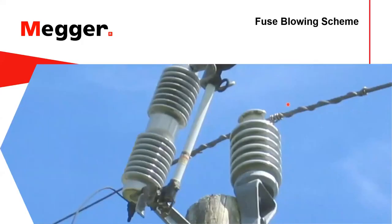Now we're going to talk about fuse blowing schemes, but before we do, let's just take a moment and recap fuse saving. Very briefly, fuse saving permits whole feeder momentary outages. The intent is to prevent longer outages to the entire faulted circuit. Fuses will accumulate a little bit of damage and at some point are subject to unpredicted failures.